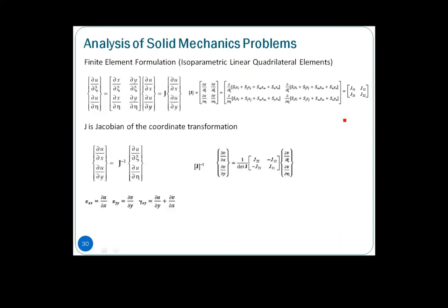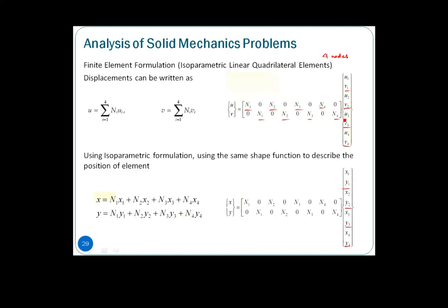All right. So making use of this, again the isoparametrics, we have our so-called Jacobian, which is what you have seen here, del X, del psi. So from here, we can find our del U, del psi, del U, del eta. Then we can find del V, del psi, del V, del eta.